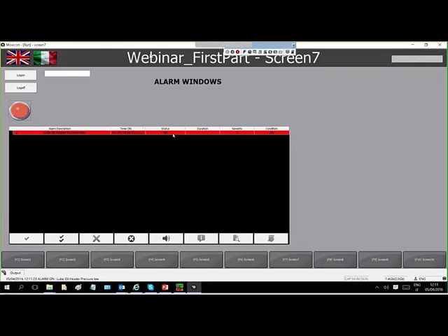Alarm on. Select the line, alarm acknowledged, no more blinking. Alarm off and acknowledged, alarm reset. Select the line, reset single, reset all. So acknowledge all, reset all. You could add here a help. So if you set a help, you could call the help from the line.